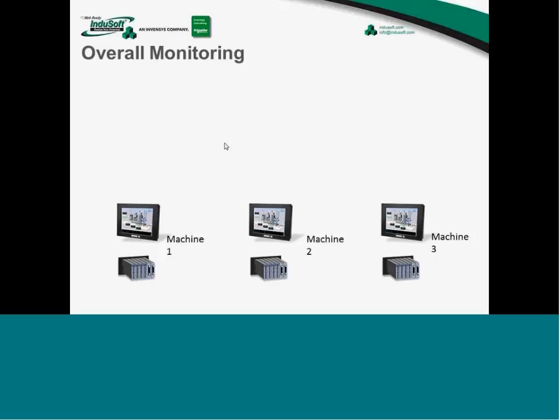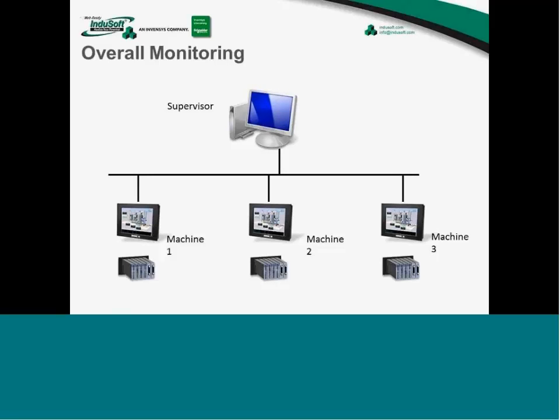And then finally you realize, hey, I'd like to collect data out of all of those. So you add a network and you add some kind of supervisory station running InduSoft Web Studio. And now maybe through the TCP/IP worksheets you can collect information from any or all three of those and send it up to a server database. And you can do that in a very easy fashion without knowing any SQL programming whatsoever. The trend worksheets and the grid object and the alarming, all can be done to a database without knowing any SQL whatsoever. So watch our videos on that if you're interested in doing that.